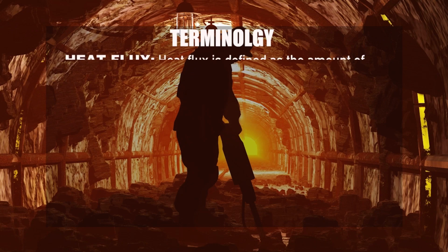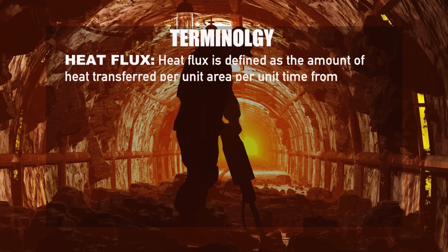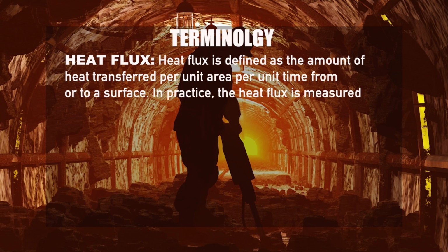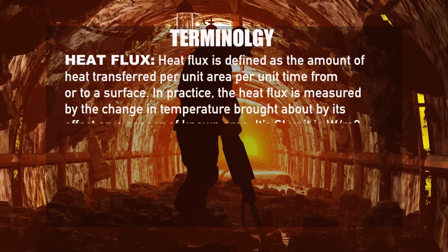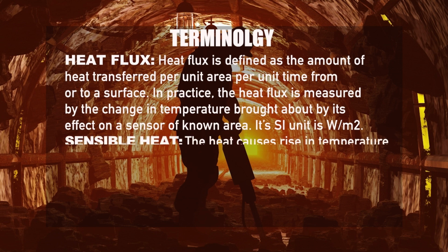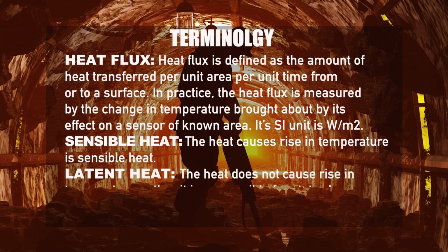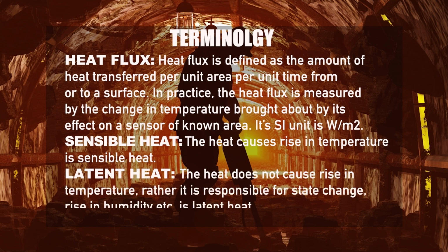Some terminology associated with heat and humidity. Heat flux. Heat flux is defined as the amount of heat transferred per unit area per unit time from or to a surface. In practice, the heat flux is measured by the change in temperature brought about by its effect on a sensor of known area. Its SI unit is watt per meter square. Basically, this is the heat radiated from a hot body into the surroundings.